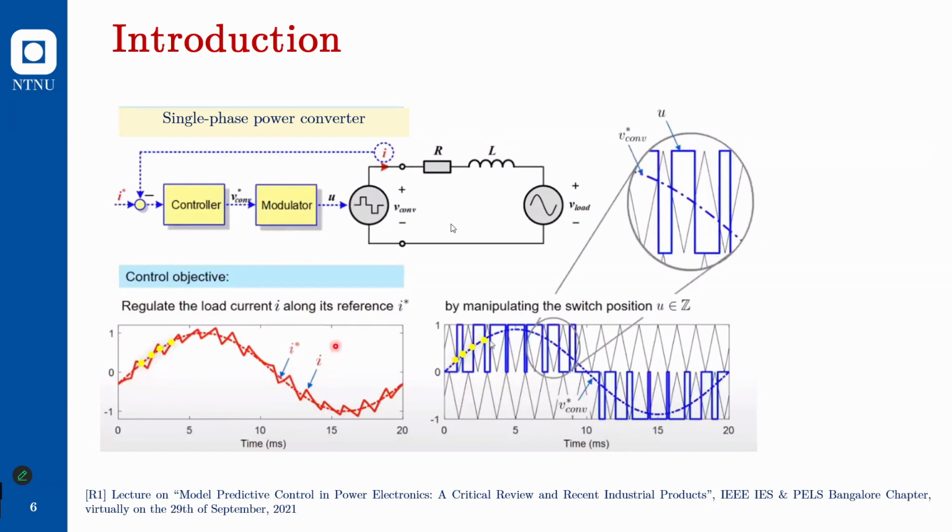That means we are actually hiding the switching logic introduced by the modulator from this linear controller, and that is very interesting because the linear controller doesn't have to know what disturbances happen during switching. It assumes it is taking a sinusoidal input and converting it to a sinusoidal reference voltage. That's how the controller and modulator work for a converter.